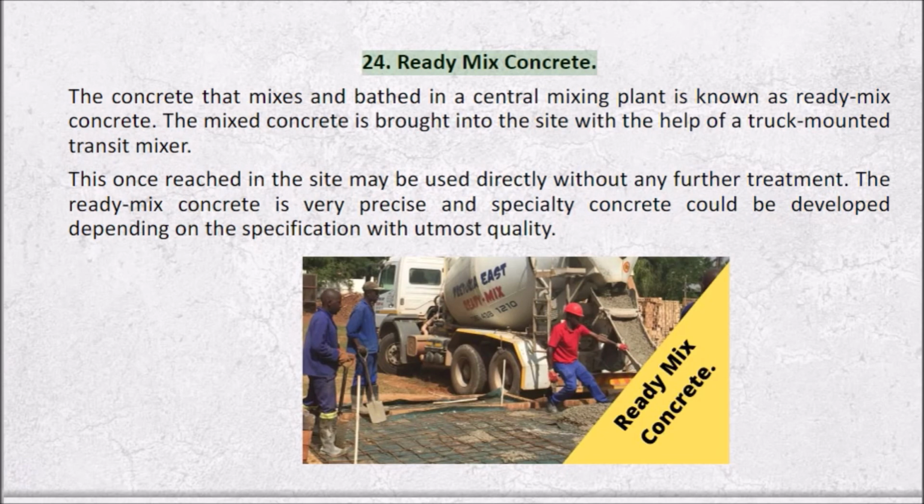24. Ready-mix concrete. The concrete that is mixed and batched in a central mixing plant is known as ready-mix concrete. The mixed concrete is brought to the site with the help of a truck-mounted transit mixer. Once it reaches the site, it may be used directly without any further treatment. Ready-mix concrete is very precise, and specialty concrete can be developed depending on the specification with utmost quality.